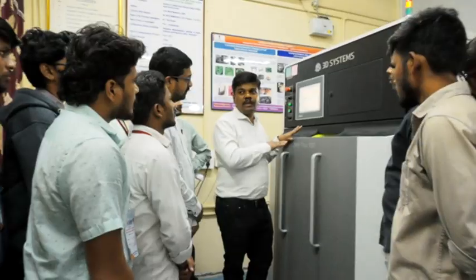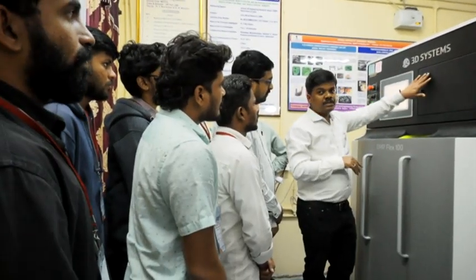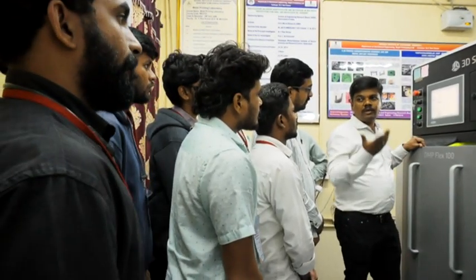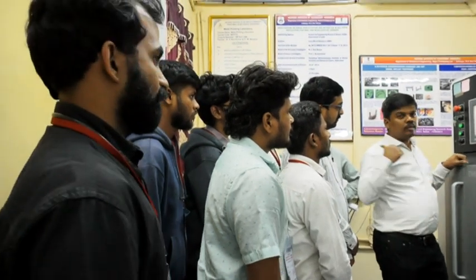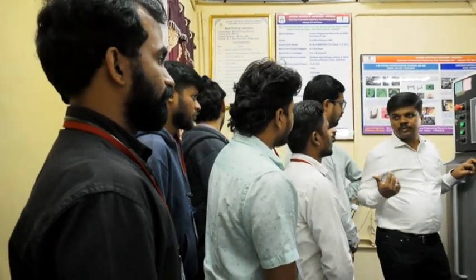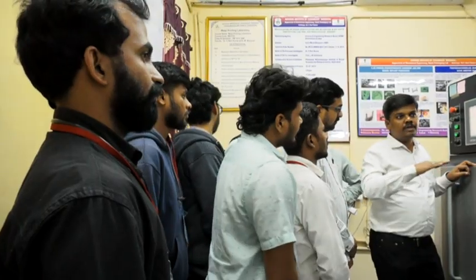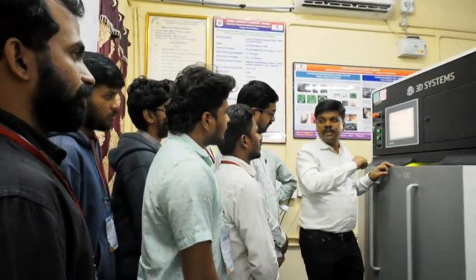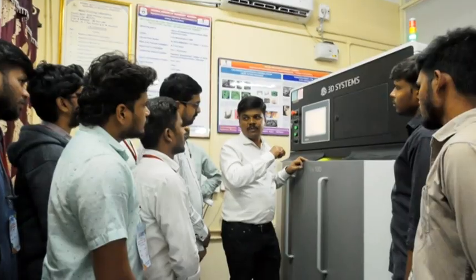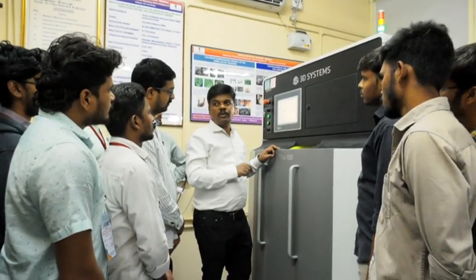We distribute a layer of powder, and with our laser system we melt it according to the geometry we are using. That geometry is created by our 3D expert software. In that we define how many layers there are, how the printing has to take place, what type of scan strategy to use, and how much laser power we have to feed.